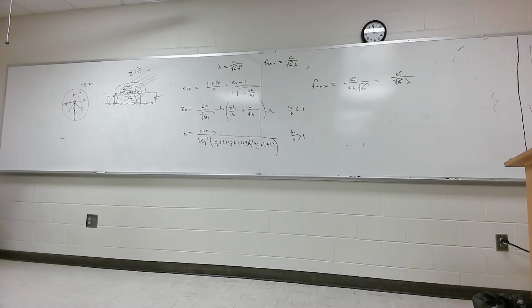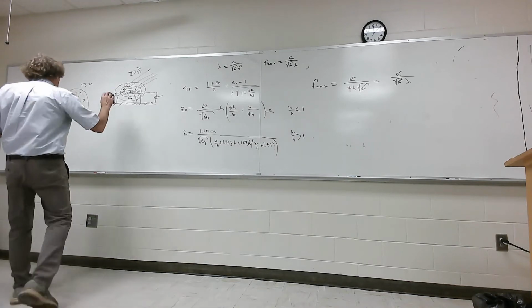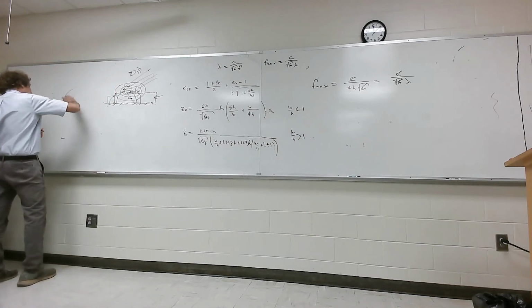Well, you've got a whole bunch of these little components you're going to be mounting, and some of them at least are going to be working at microwave frequencies. So the way you get around a lot of really expensive stuff like coaxial cable hookups is using microstrip. That's the real goal. It's a cheap, effective way to do this. Now, with engineering it, here's where the fun begins.